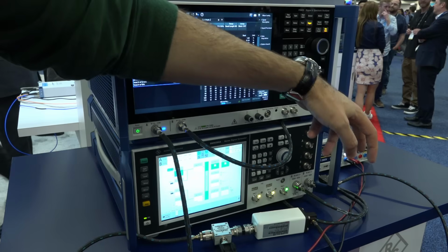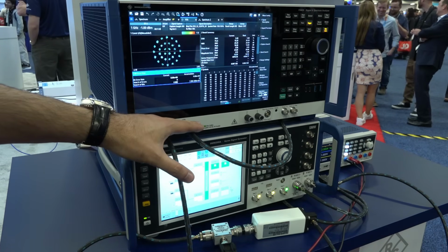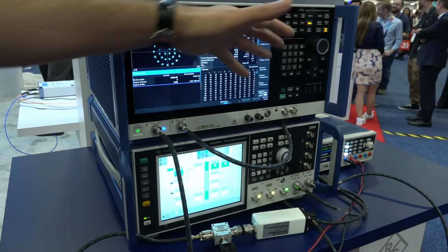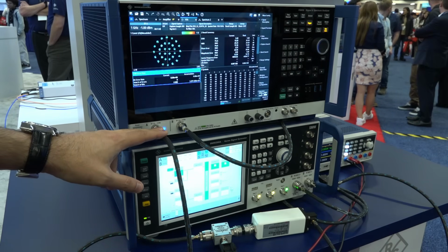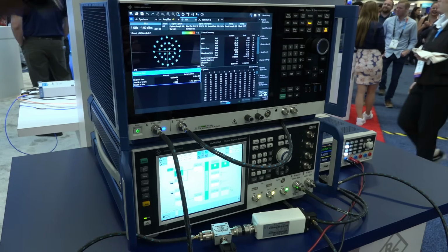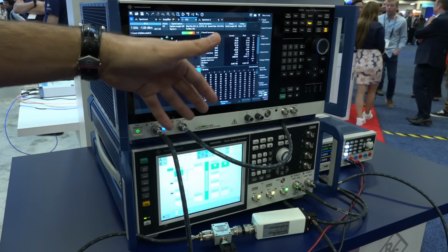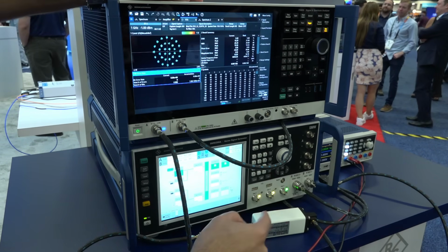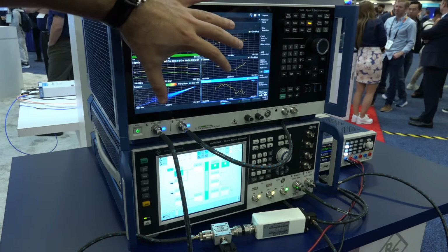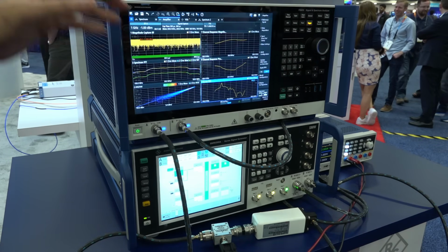So the signal, the IF signal at low frequency, is split at the input, fed into one channel of the spectrum analyzer. The output of the mixer is now at a different frequency. In this case, it's at 11 gigahertz. You feed that into another channel of the spectrum analyzer. Now they're in two different carriers, but everything is completely self-aligned to the front of the instrument. Now you can run correlation algorithms and understand what that mixer is doing to the signal coming in, and then that becomes a complete characterization of that nonlinear device using a single instrument, fully aligned in the front end.